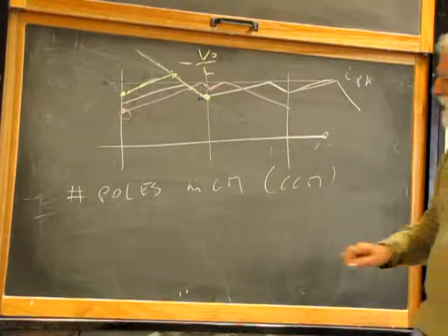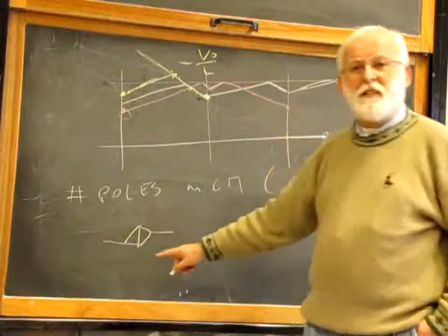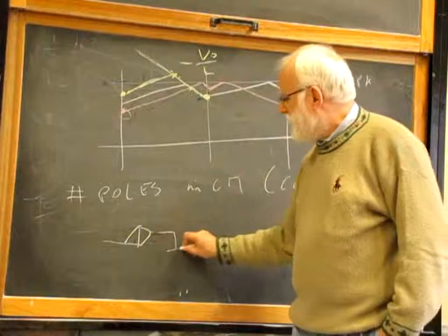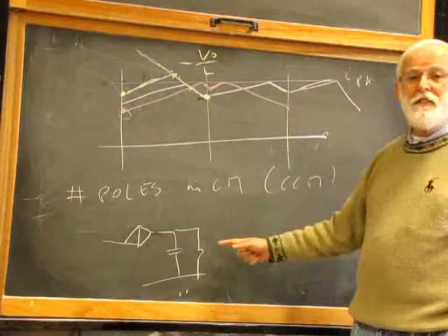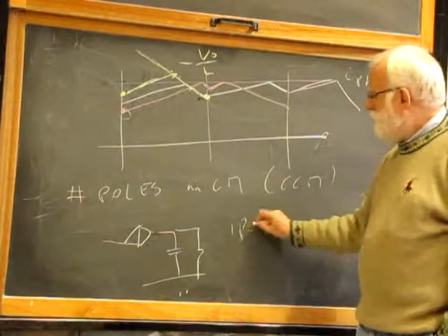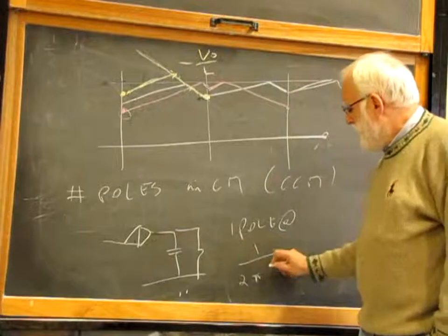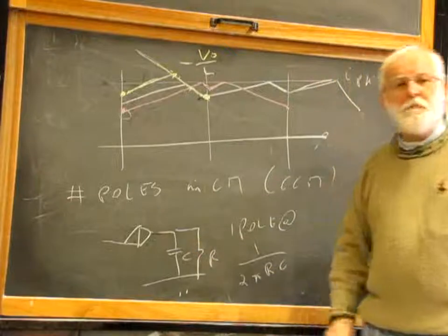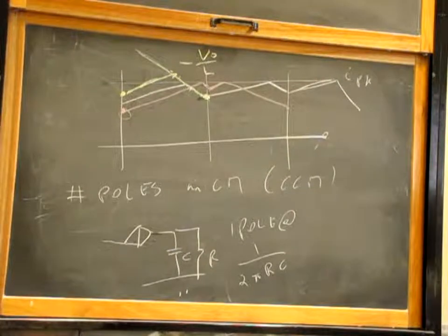Well, we found out last time that a buck converter, a buck-derived converter, looks like more or less, with a good approximation, as a controlled current source with our output capacitor and load resistance, like this. And so we have one pole. One pole at 1 over 2 pi, the load resistance and the output capacitance. And this is what you need for practical design, most of the times.